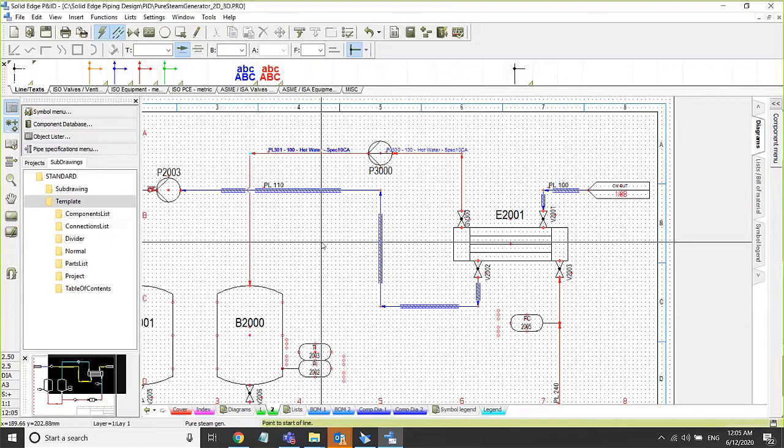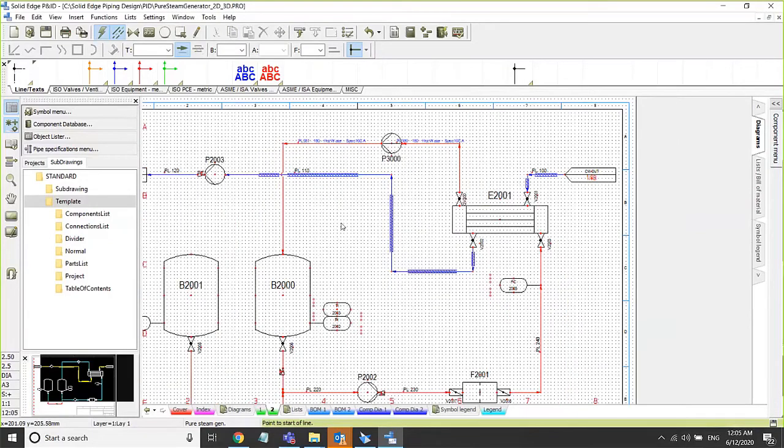So as I have created the pipelines by placing the components and defining a particular size for the pipe, the next thing you'd like to do is check whether your schematic is in accordance with your standards. You want to validate your design against design rule checks.